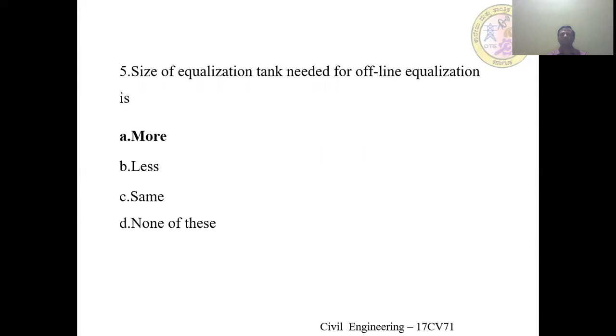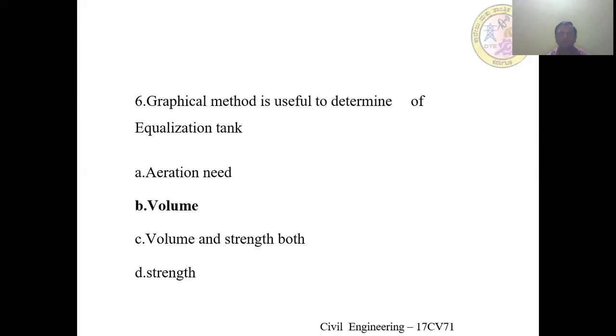The size of the equalization tank needed for offline equalization is more, less, same, or none of these? The size of the equalization tank needed for offline equalization is more, because it depends on the volume of the treatment process or the volume of wastewater to be discharged. The graphical method is useful to determine the equalization tank volume.